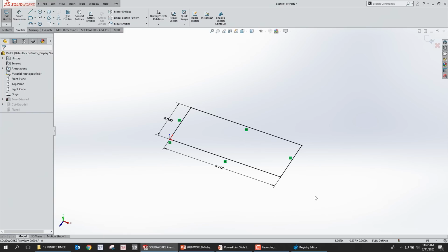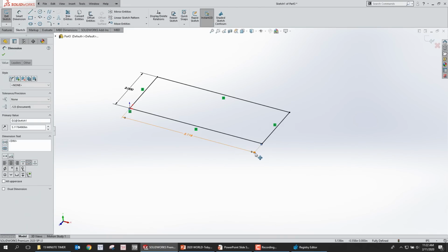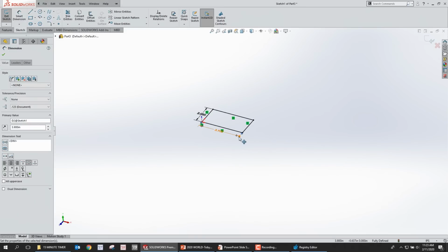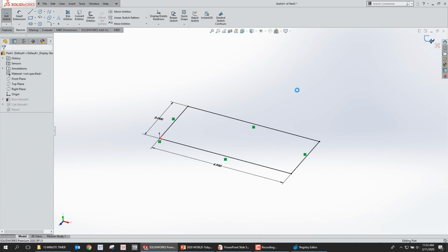So the question is, how much control do we have over the ruler, and what can we do to refine that and maybe even incorporate inch increments into it? I mean, we could experiment with it, maybe get in there and adjust your settings for fractions and round to nearest. But this slider is based on how far out you're zoomed. So you're going to see different increments depending on how far out you're zoomed, and then you'll be able to snap to those increments. It's also based on where you are on the ruler. So like if you're out here, it doesn't snap, but if you're on these little notches, it does snap. So there is some snapping you can do when you see those rulers. Yep, great question.